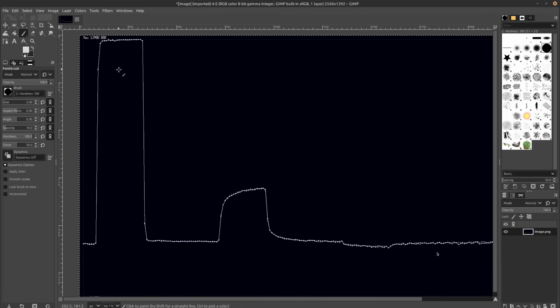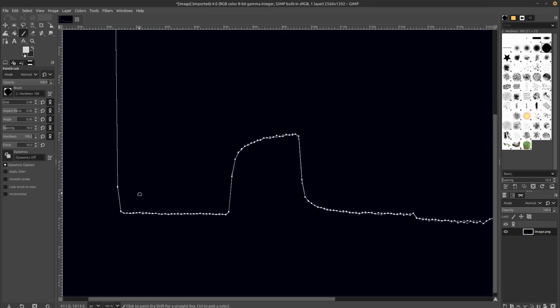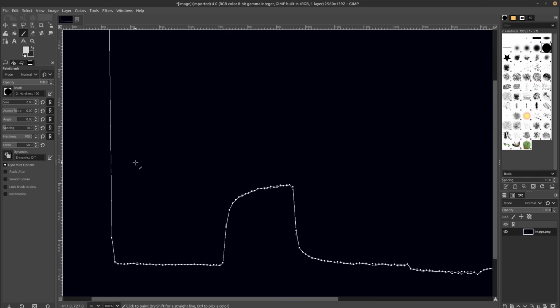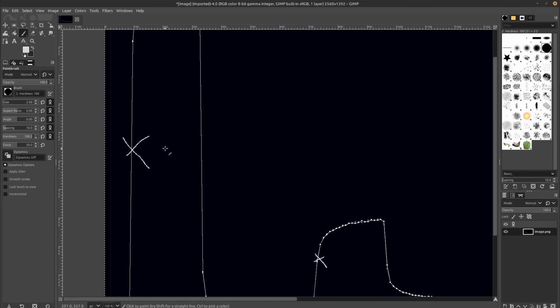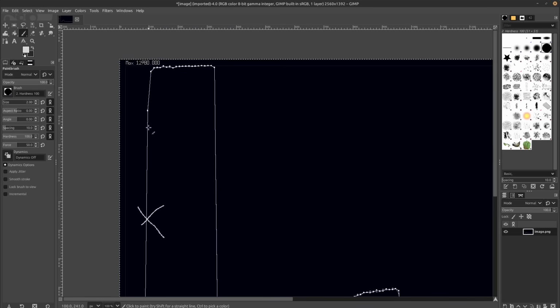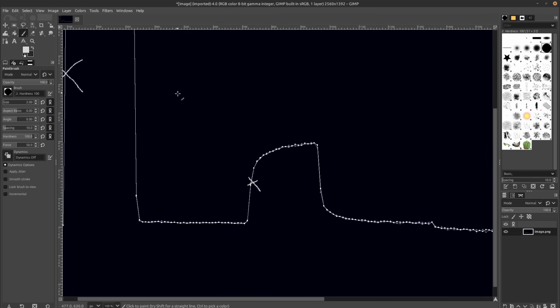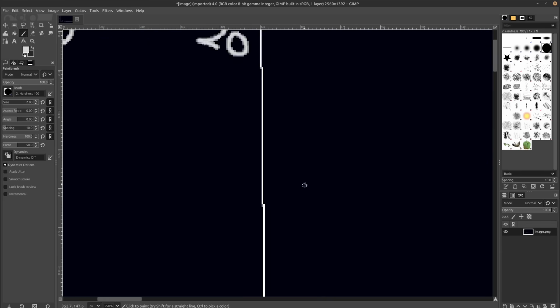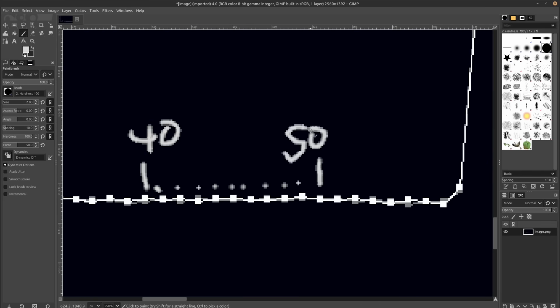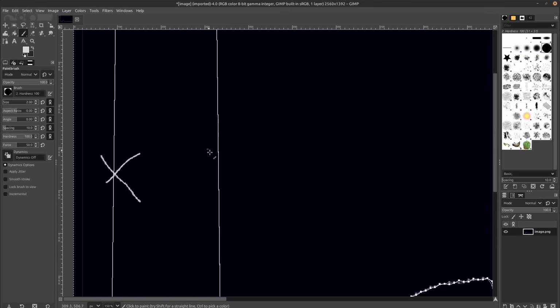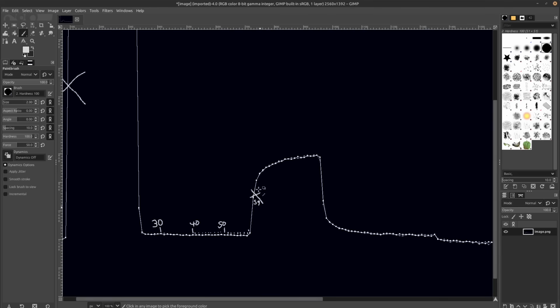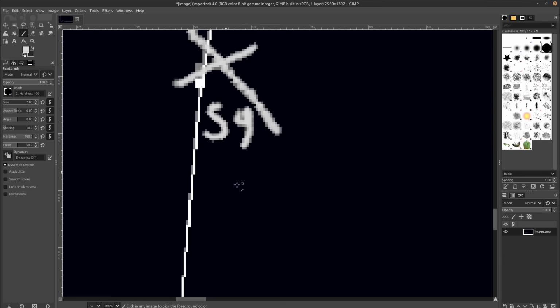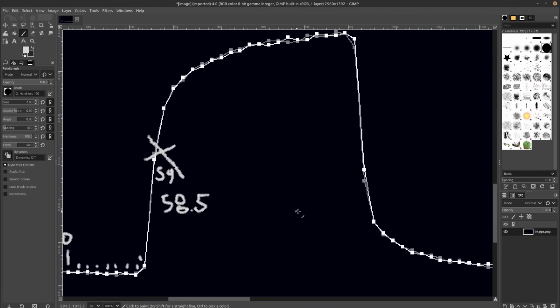So what we're going to do is we're going to take the capture here, and I'm going to start at, I guess it's about the 50th percentile, so right there, going to right there to, I don't know, maybe about here, and we'll just see how this works out. So I'm going to start by counting the number of 1/48 millionths of a second from here to here. It's actually a little bit less than 59. Maybe 58.5. That's 58.5 48 millionths of a second.